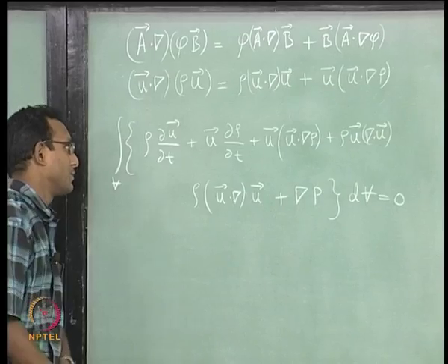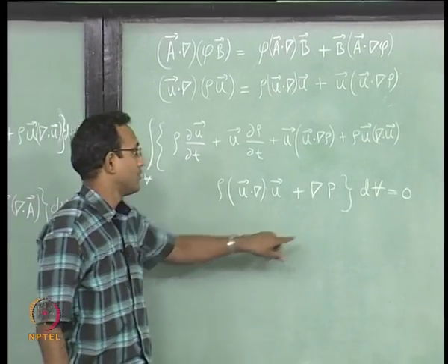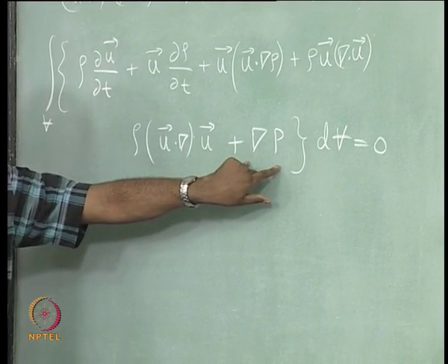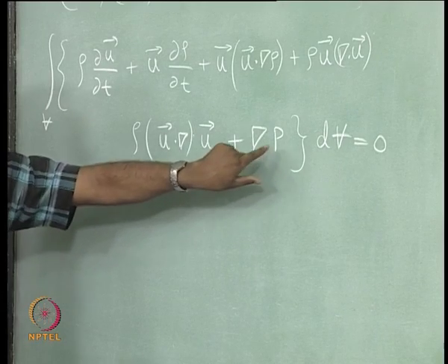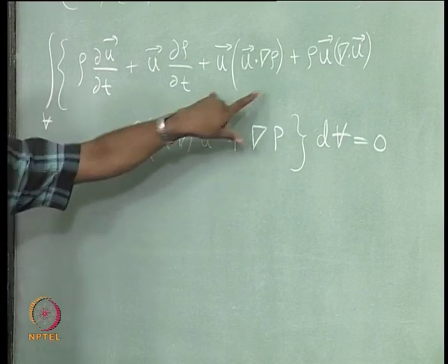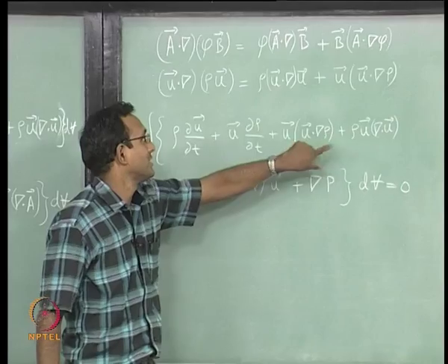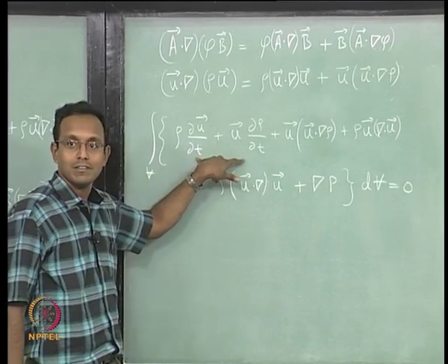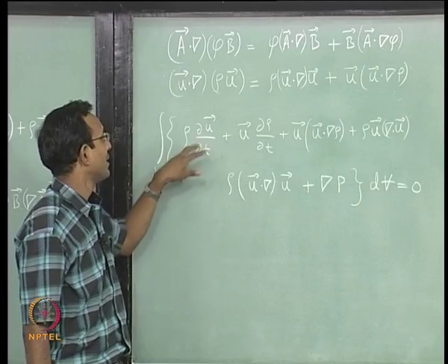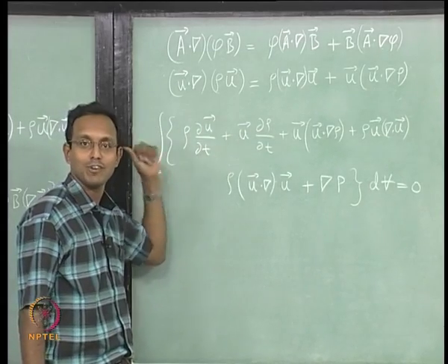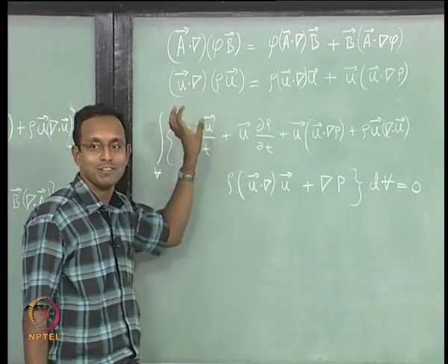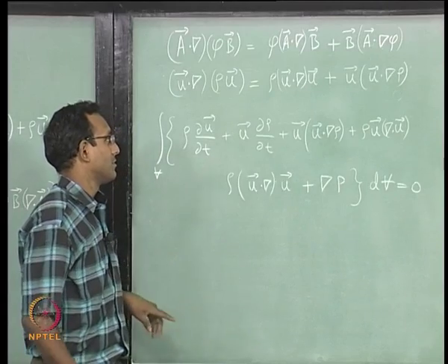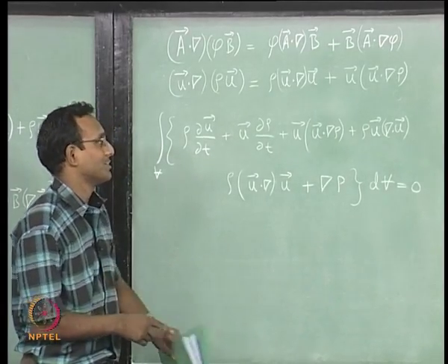This whole thing is one equation, of which we know that this is your del p term that is coming from tau tensor dot n dS integral converted to volume integral. These are the 3 terms which we just talked about, of which 2 of them are just sitting here directly above. This is the first unsteady term. Now the time derivative is operating on individual terms instead of what we had before as a group. Dou by dou t of rho u together we had, it is operating on individual terms. That is the whole thing we have. Now we want to group it in a nice fashion.